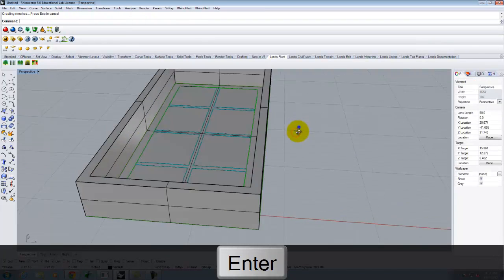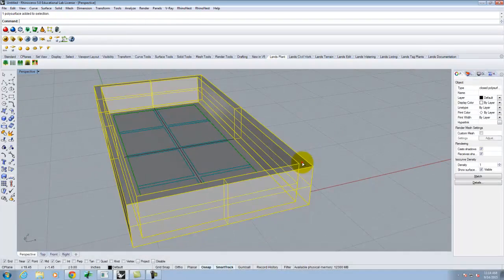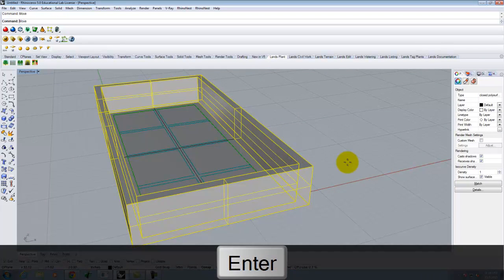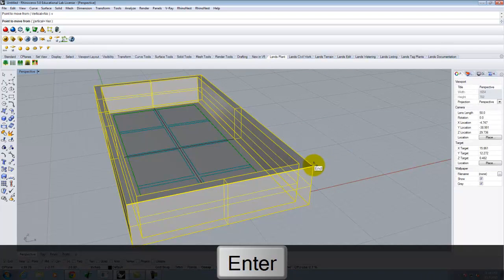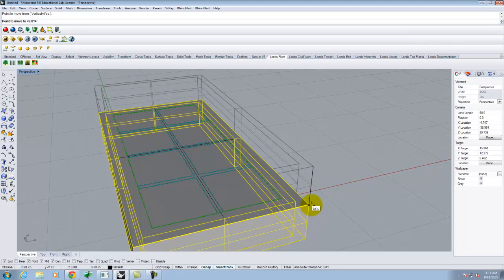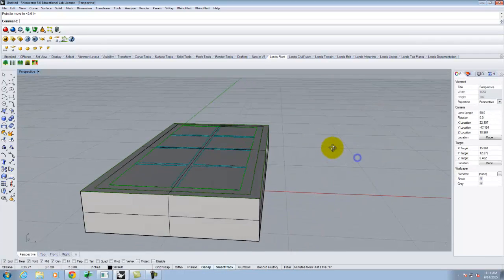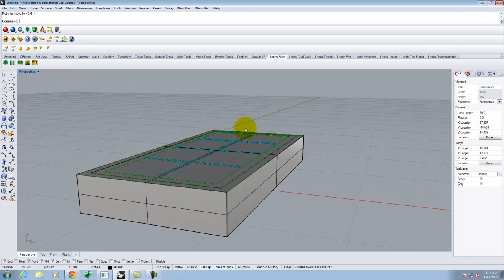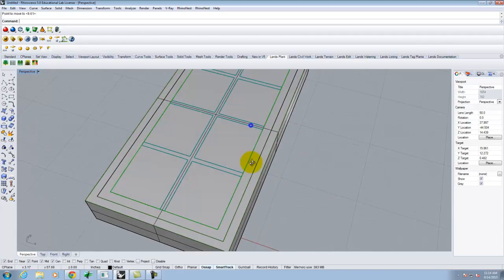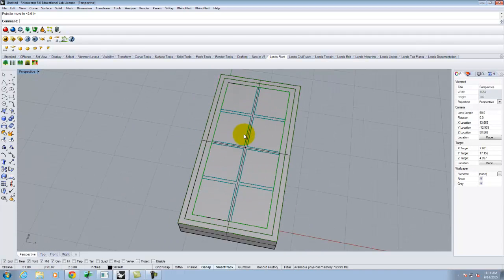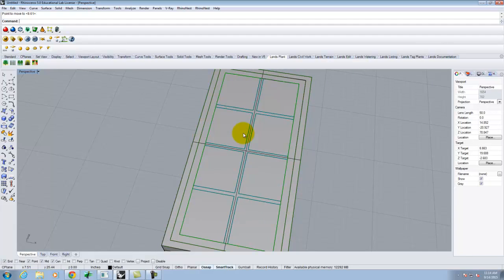And that gives me the initial frame. Okay? Now I'm going to go ahead and move this down. So I did move and then V for vertical. And we're going to go down so that it's actually below, because it's going to make making this window a little bit easier. Okay? So this was a casement window, which meant that it opens like a hinge, like a door would open. So I'm not going to model a double hung. This is actually a little bit easier to model.